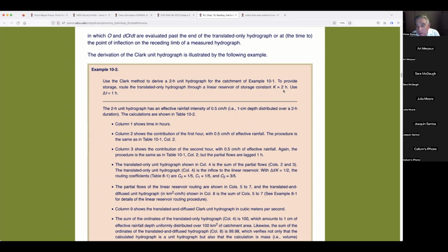So there's a standard for this. The delta T over K should not be greater than 2. So in this case, it's 1/2, which is fine. You could still have 1, will get less diffusion, but it still works. 1.5 will work, but 2 will start to jump around and give you garbage. If you use 3 or 4, it will blow up on your face.